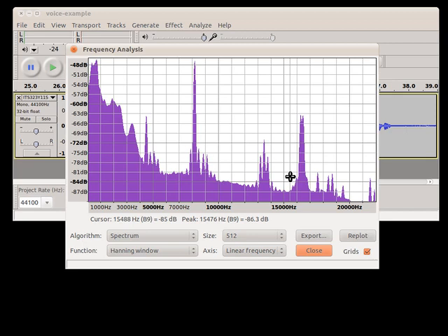So when we talk about a signal, there are two parts to it: the frequency, or usually the center frequency, and the bandwidth, the range of frequencies. Our input signal had a range of frequencies from 0 to 20 kilohertz, let's say at a center frequency of 10 kilohertz. The signal sent from our wireless transmitter to the receiver has a bandwidth of 200 kilohertz from 670 to 670.2 megahertz. So the center frequency is around 670 megahertz, 670 million hertz, as opposed to 10,000 hertz. So what my wireless transmitter does is shift the input signal and the original voice data to a different frequency, and it does modulation.